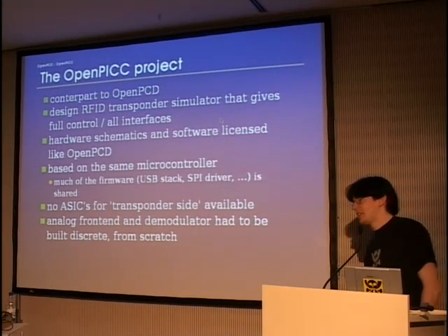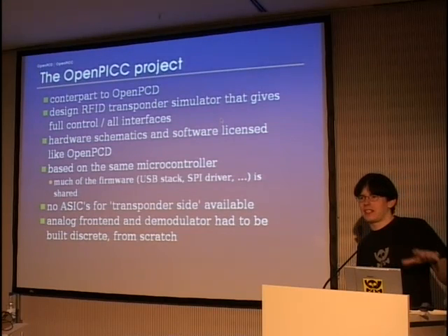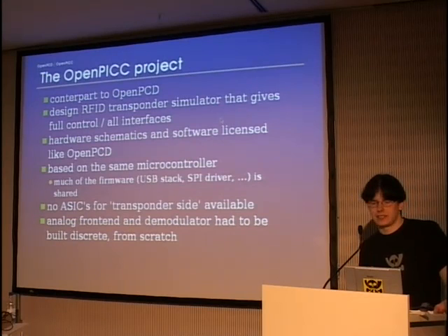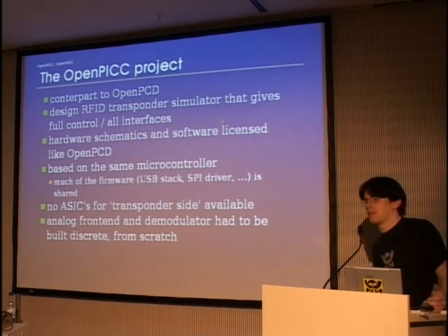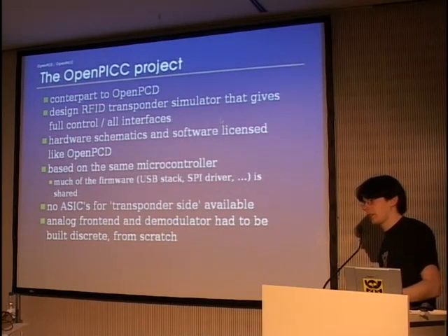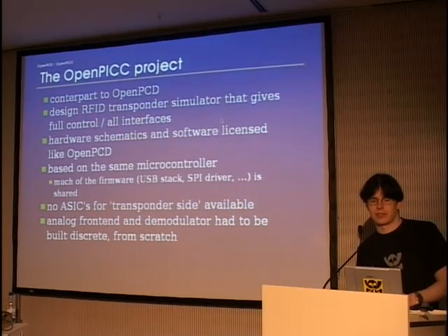The OpenPICC basically tries to emulate existing RFID cards, and again have something that provides you all the interfaces where you can get to all the signals at any level, where all the hardware schematics are available, where all the device firmware and host software is available under a free software license.